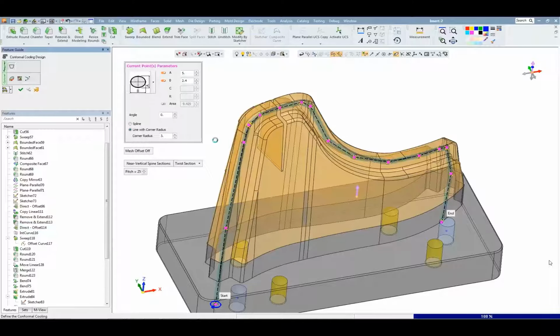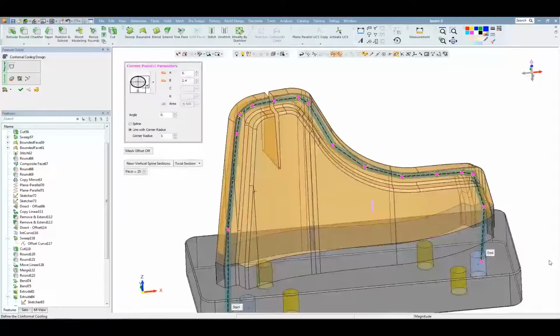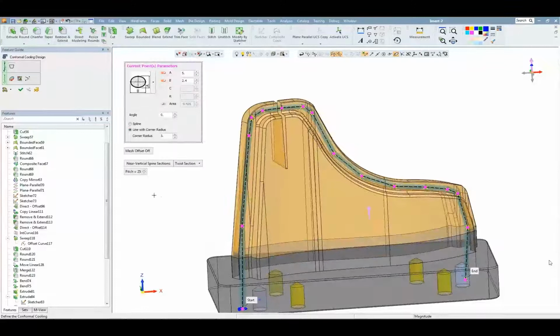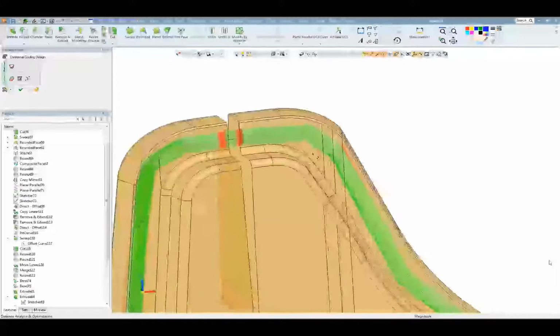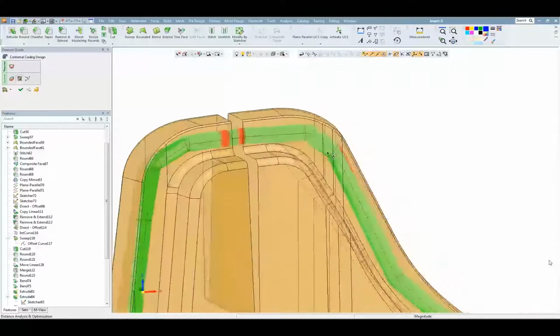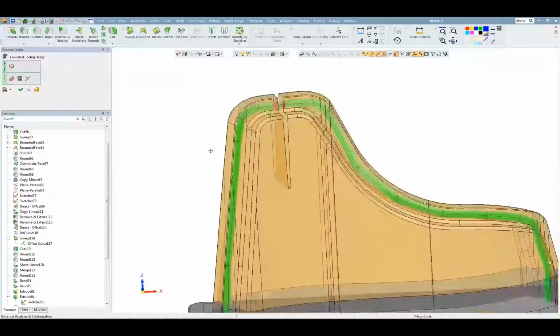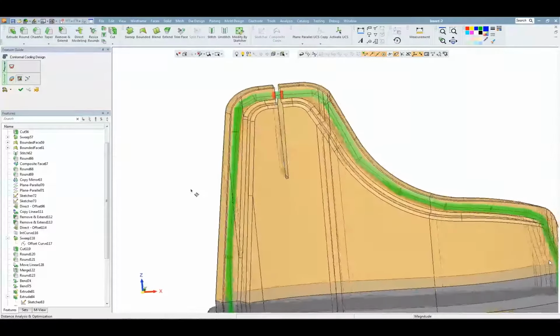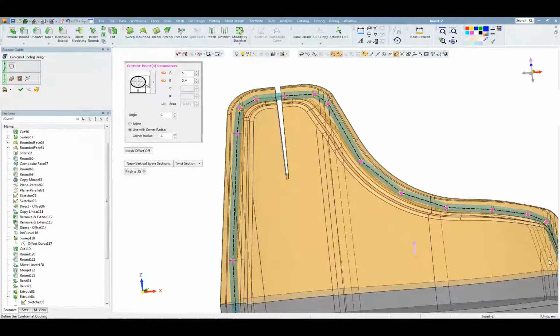Now we are looking at procedurally generating the cooling channel, and you can see how it's been created along the spline arc here. We're going to do a quick check to see if there's anything wrong with this design, and we can obviously see there is a slot into the part here, which is being highlighted as it's going through the outside of the geometry. And we're just going to go back and see how easily we can edit this geometry to be suitable. So moving back to the control tool here, we can actually just pull the geometry down into a more suitable position here.